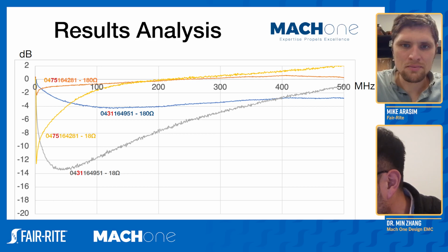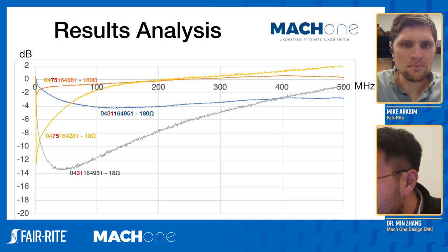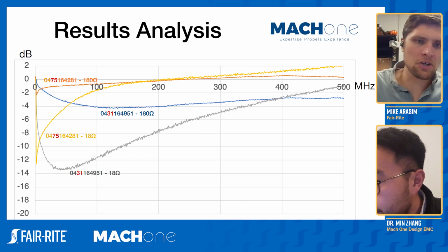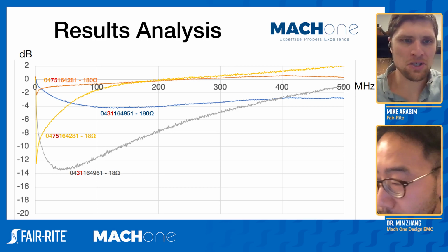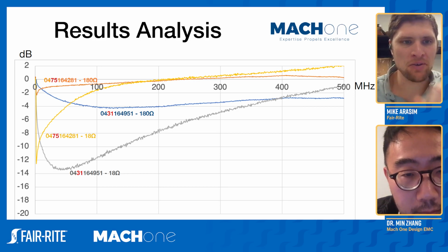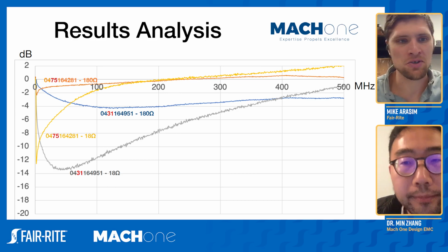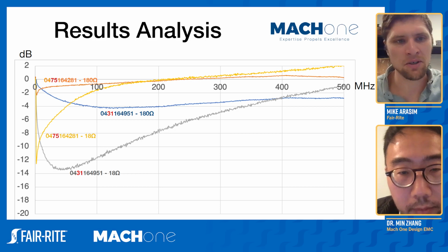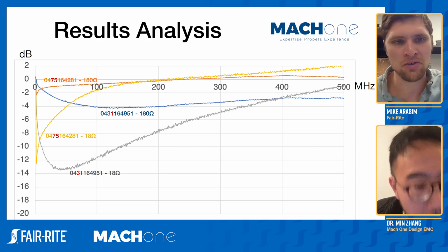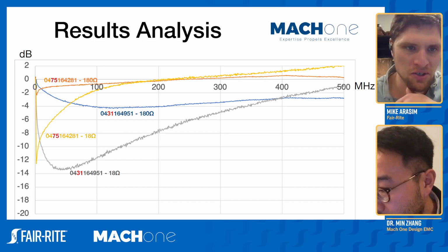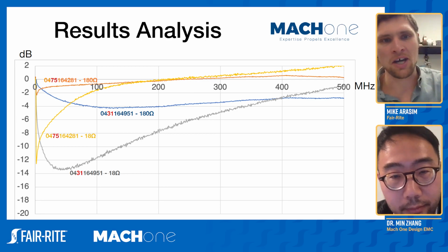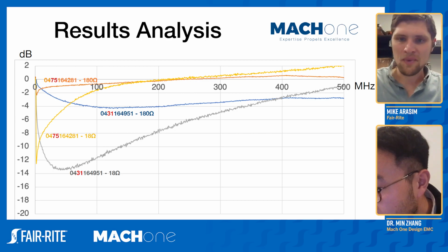Yeah, because the other thing I noticed too, the frequency on the low impedance path looks to be shifted. The peak attenuation frequency looks to be shifted down into, I don't know, maybe 50 megahertz, 30 megahertz, somewhere in that range. Whereas here it looks like you're up over 100 on the high impedance. That's right. Yeah, that's right.